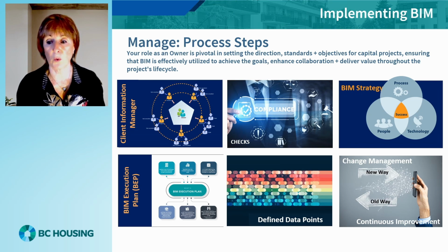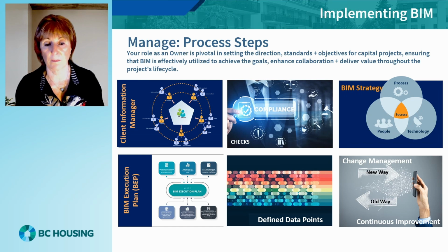Has the team recorded in the BEP how and who is going to do what to meet these requirements? Have the defined data points been established, understood, and the timeline for when the information will be present in the model dataset agreed? There is a need for both internal and external change management to support the evolution of a BIM process.